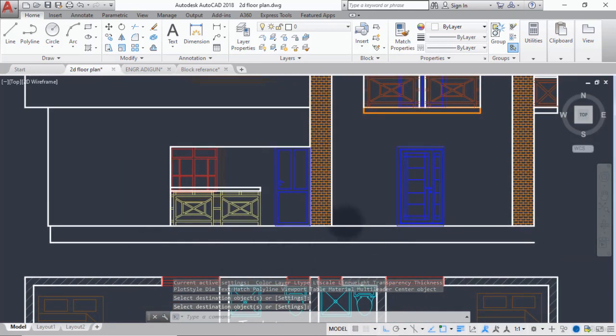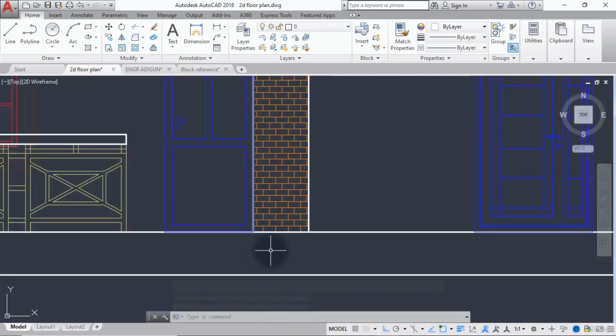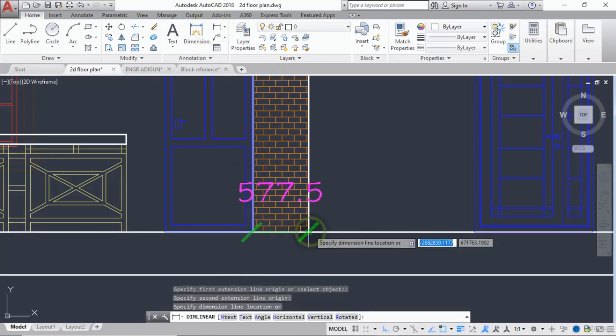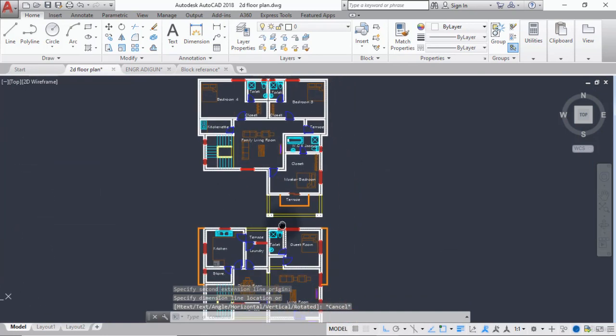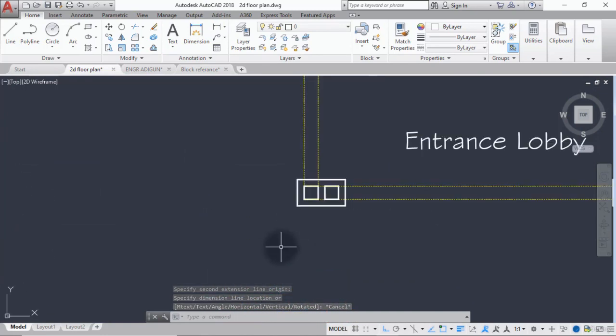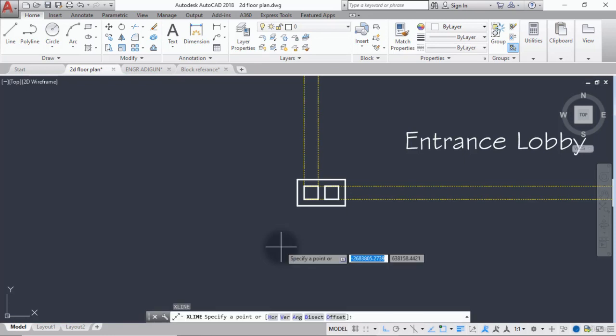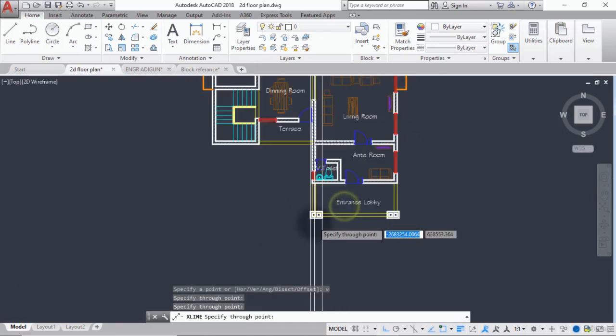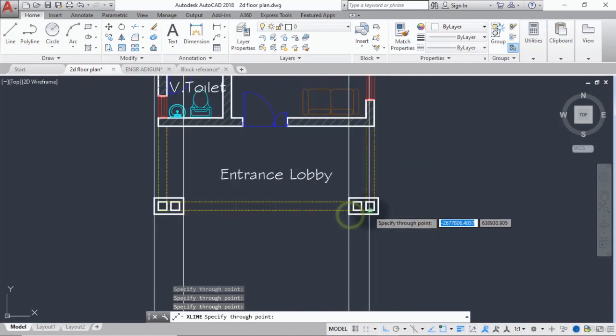So the next thing we want to do again is put a base for our column here now. So to do that now, we check what is the distance from this point to this point. So we'll just come here to our ground floor and draw our X line. Since we already have the plan for the base, vertical, select this and this, this and this.